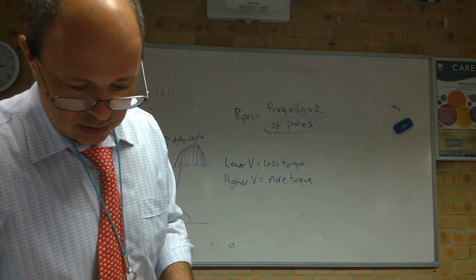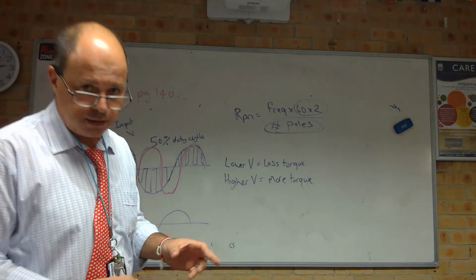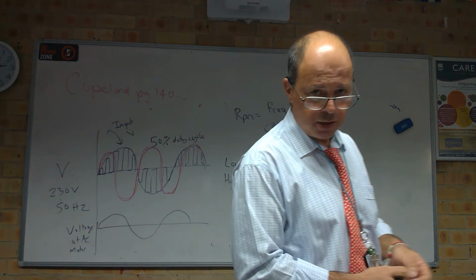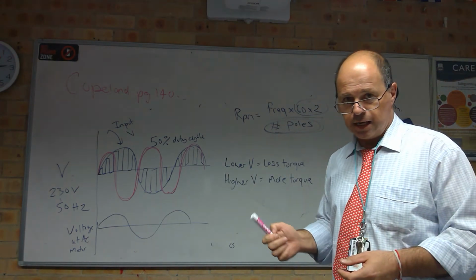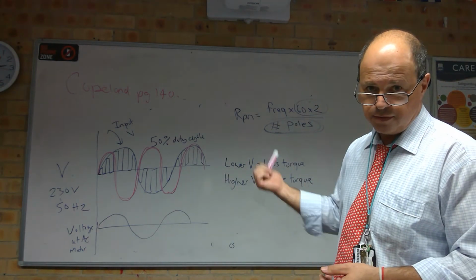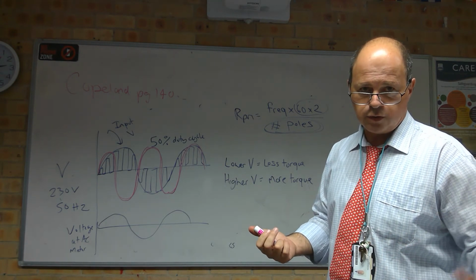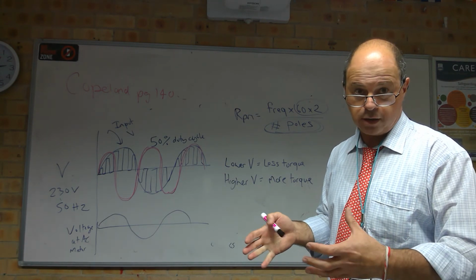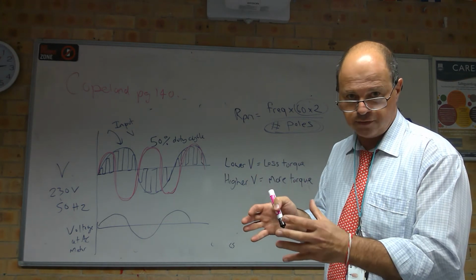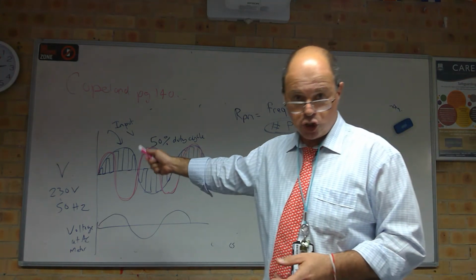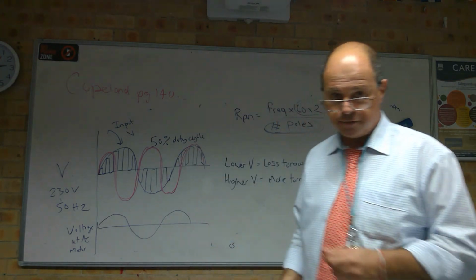I think it's a fascinating area of electronics and electrical engineering, it's control technology, and it's come ahead in leaps and bounds from the early days when we had giant transformers because we didn't have any way of switching the mains voltages. That's why now your consumer electronics has such tiny transformers, because they have what's known as a switch mode supply. They chop up your 50 hertz and make it a much higher frequency.